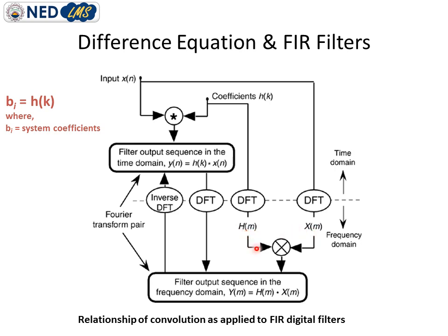So what we have to do is just multiply the two frequency domain versions to get the final output in frequency domain. And if we want to transform back into the time domain, for example if we want the output in time domain, we just take the inverse FFT of this final output to transform it back into the time domain.